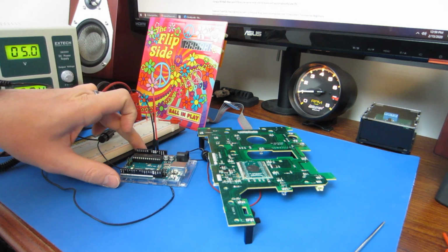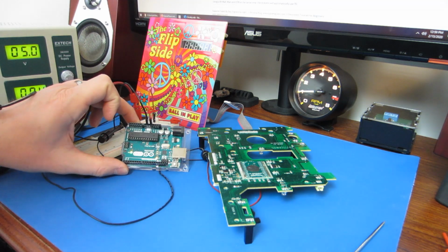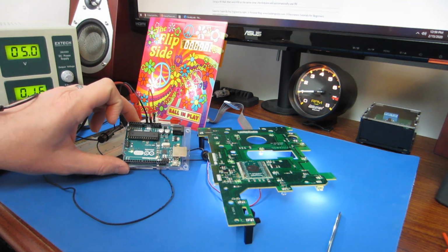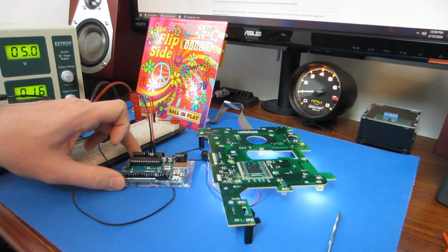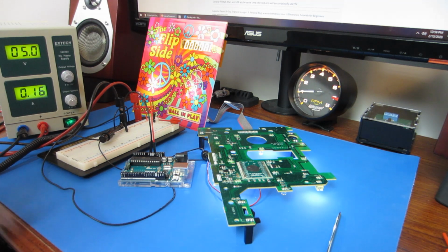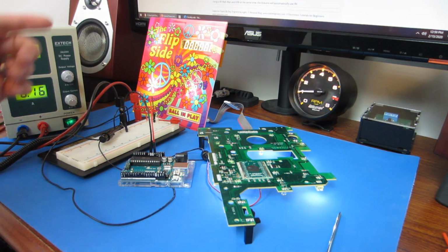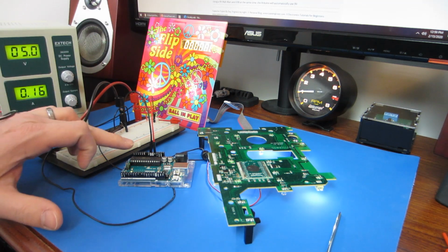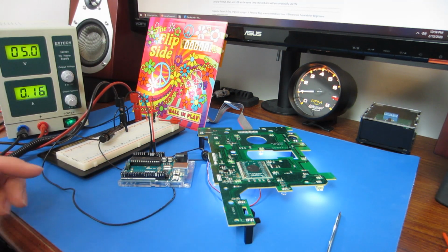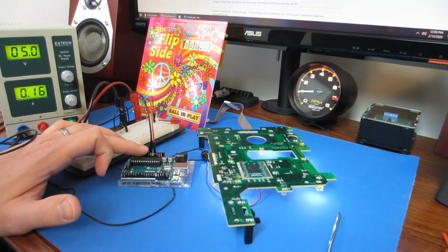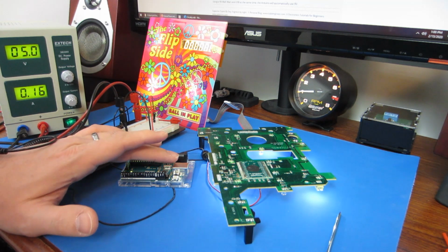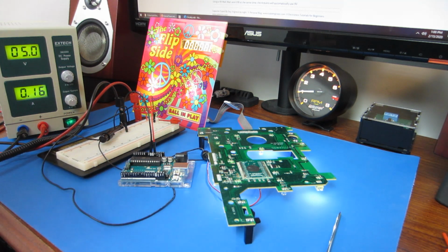There we go. So you can see it's powered on. Let's test to make sure, yep, that powers on too, so we're good to go. One thing to be careful of if you're powering an Arduino directly off of regulated 5 volts using the 5-volt pin is that you don't want to connect voltage on this 5-volt pin and also connect your USB, because at that point you've got competing power sources.